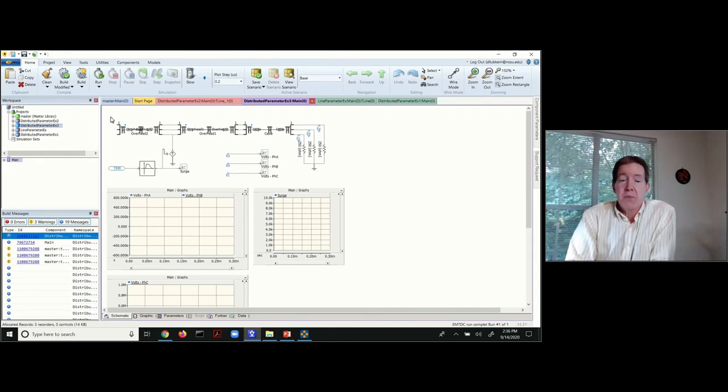Well, you need to use this transmission line splitting module. You put it at the end of the line section and break out phases A, B, and C. Then once this is broken out, you convert back to the three-phase connection model, and then you finish out the rest of that overhead segment. So some of the overhead impedance is on the left, and some is on the right.